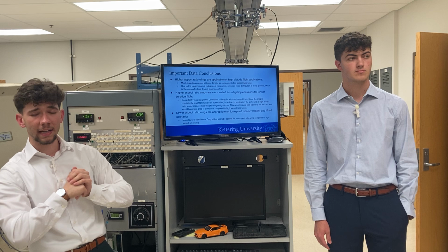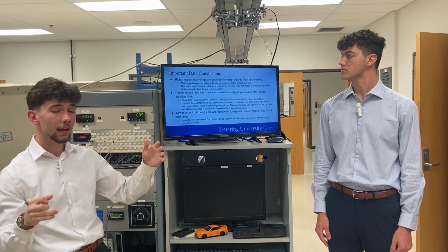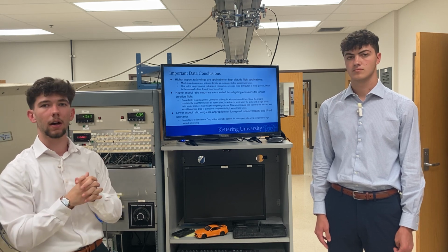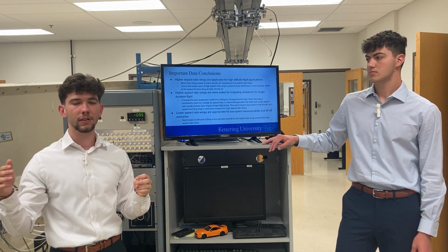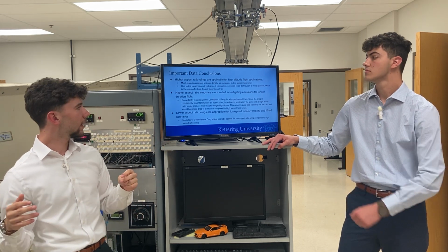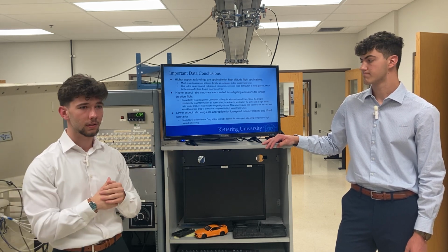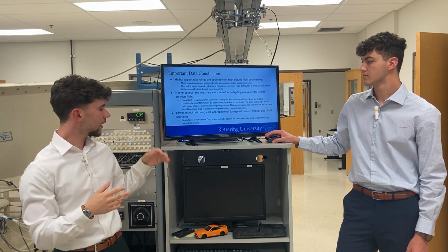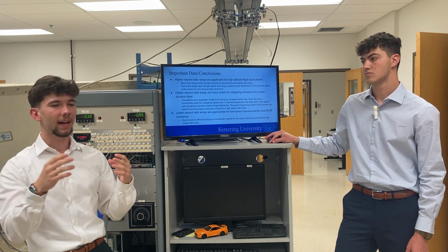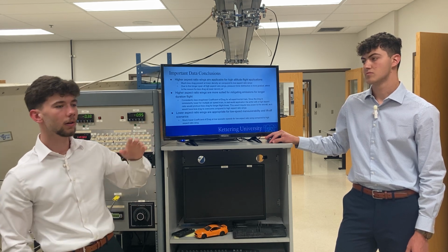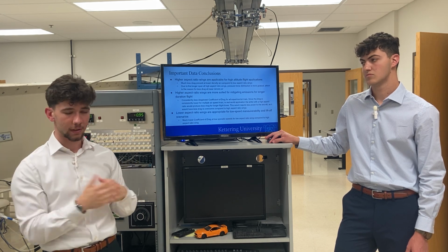Also, higher aspect ratio wings are more applicable for high velocity, longer duration flight, as well as would be better for mitigating emissions from an aircraft. And the reason for that is because it consistently had a lower coefficient of drag and lower drag forces, it would then require less power from the motor of the aircraft in order to overcome those drag forces and mitigate emissions. Lastly, as Adam stated, the lower aspect ratio wings are more appropriate for maneuverability, as we see with airplanes from air shows, as at lower airspeeds, they were able to perform better with the coefficient of drag.